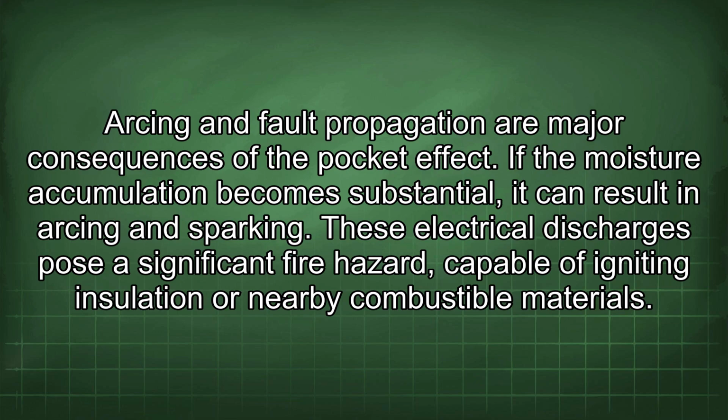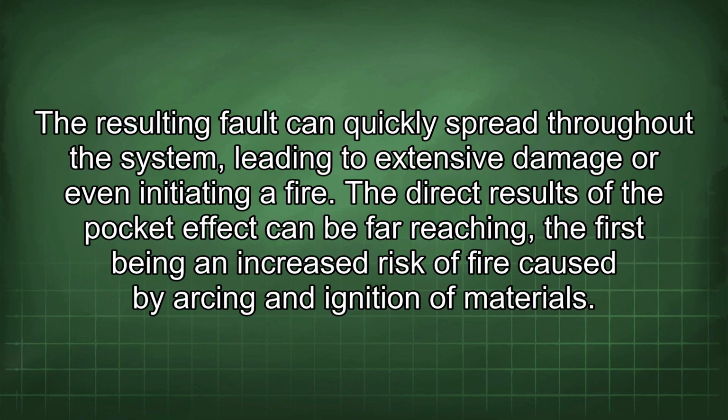Arcing and fault propagation are major consequences of the pocket effect. If the moisture accumulation becomes substantial, it can result in arcing and sparking. These electrical discharges pose a significant fire hazard, capable of igniting insulation or nearby combustible materials. The resulting fault can quickly spread throughout the system, leading to extensive damage or even initiating a fire.